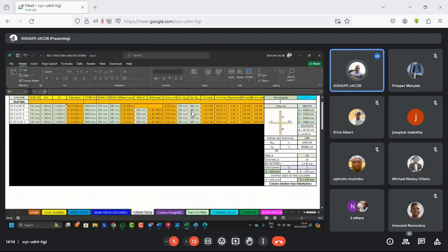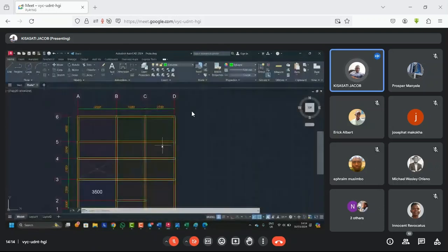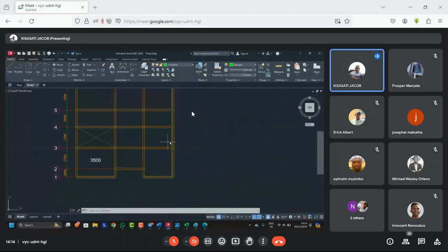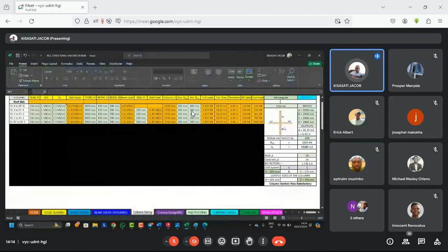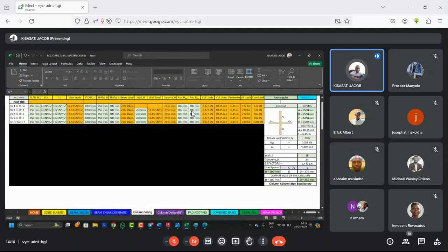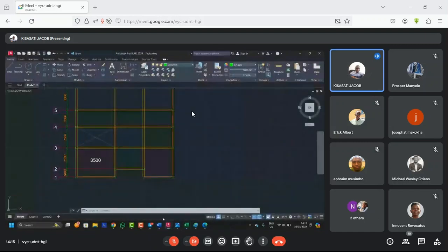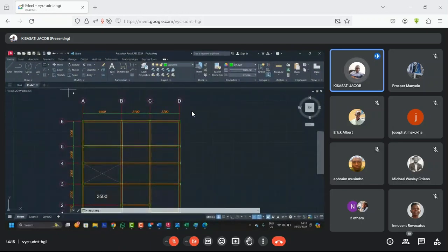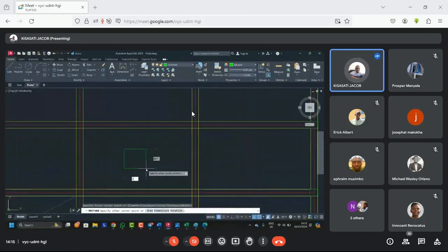That's okay. Then AB, the vertical ones, AB is 25 and 35. Okay, this is noted. After doing this, you'll get 200 by 275, so we can actually use 300. Thank you for that, because any error will lead to oversizing of your columns. So for this one, we'll just use 200 by 300. So I'll just type this column here, 200, then tab, 300.